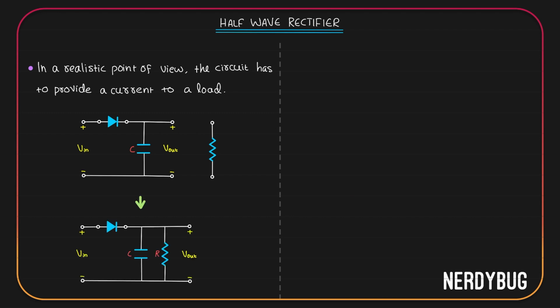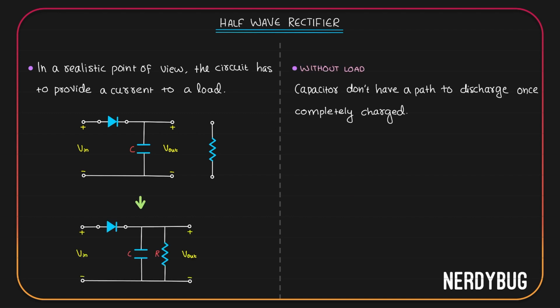Without the load, when the capacitor got completely charged and the diode became reverse biased, the capacitor did not have any path to discharge anymore. That is why we got a constant voltage after that. But when the load is connected, the capacitor has a path to discharge even when the diode is replaced by an open circuit. It will discharge through the resistor.